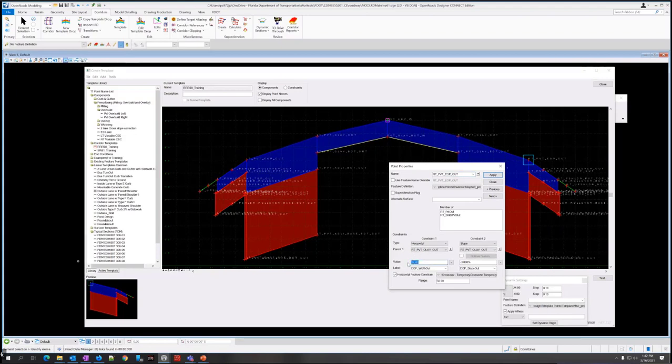So that's my lane width essentially. So let's change that to 1. Well, this isn't really a lane. I'm just really widening. It's going to vary because I have a feature constraint over here. So I'm going to set this slope to -2%. This is normal lane.